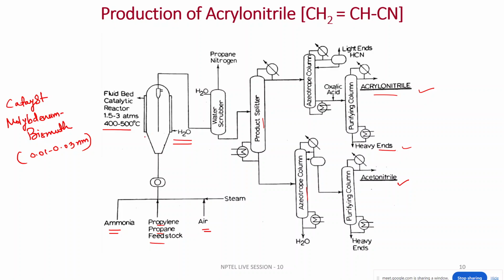Now you need to also remember one thing, that to get more of the desired product, we need to minimize the sulfur content of the feed that we are introducing, because this sulfur can be highly reactive and can highly degrade the catalyst performance over the period. So as much as possible, we prefer the desulfurized feed to be fed to the reactor.